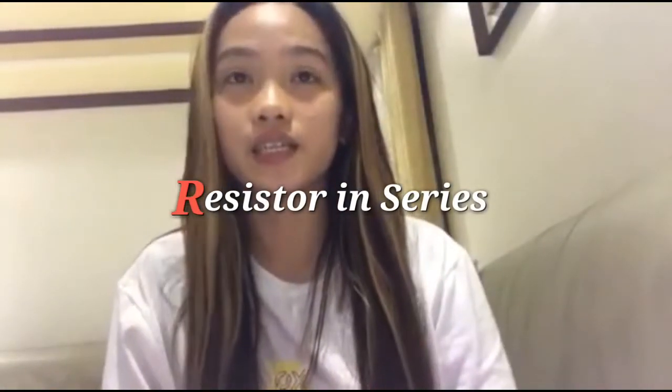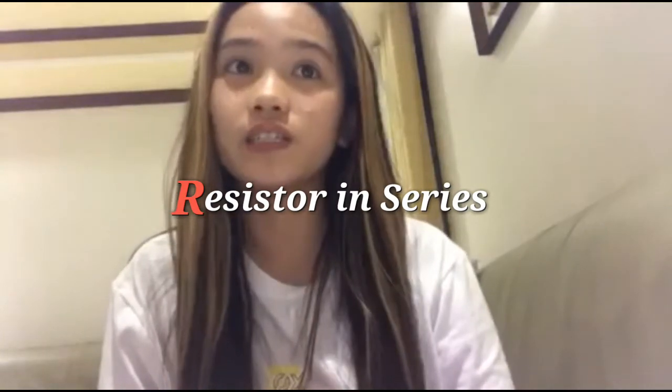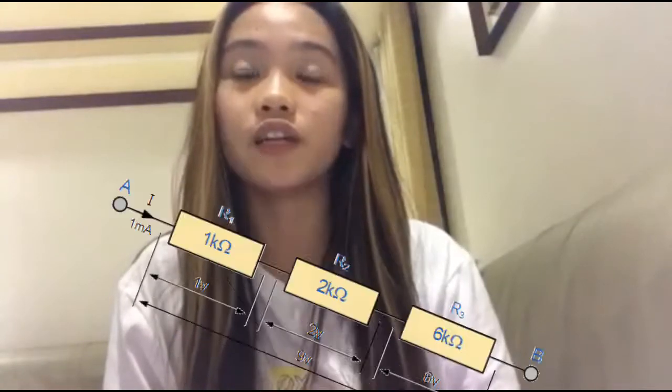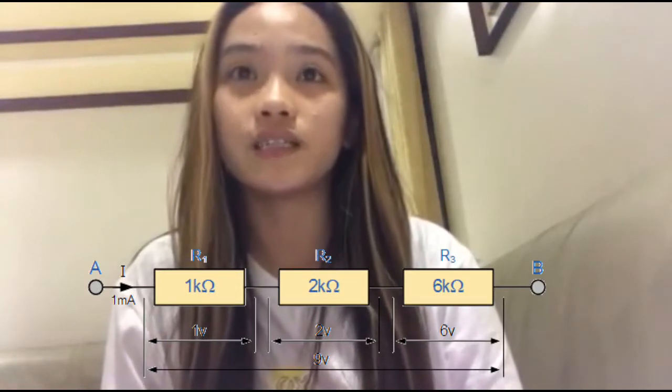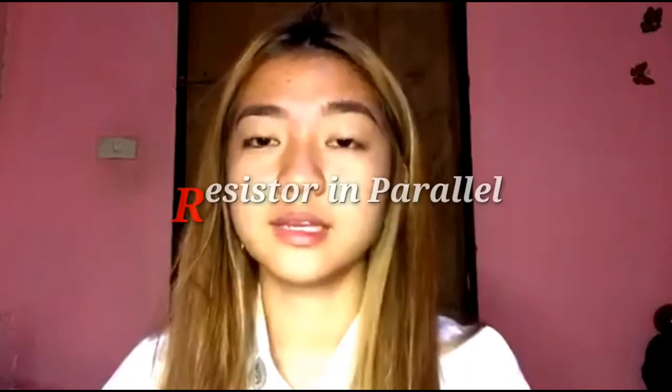In a series circuit, the output current of the first resistor flows into the input of the second resistor. Therefore, the current is the same in each resistor. Resistors in parallel. Resistors are said to be connected together in parallel when both of their terminals are respectively connected to each terminal of the other resistor or resistors. Unlike the previous series resistor circuit, in a parallel resistor network, the circuit current can take more than one path, as there are multiple paths for the current.